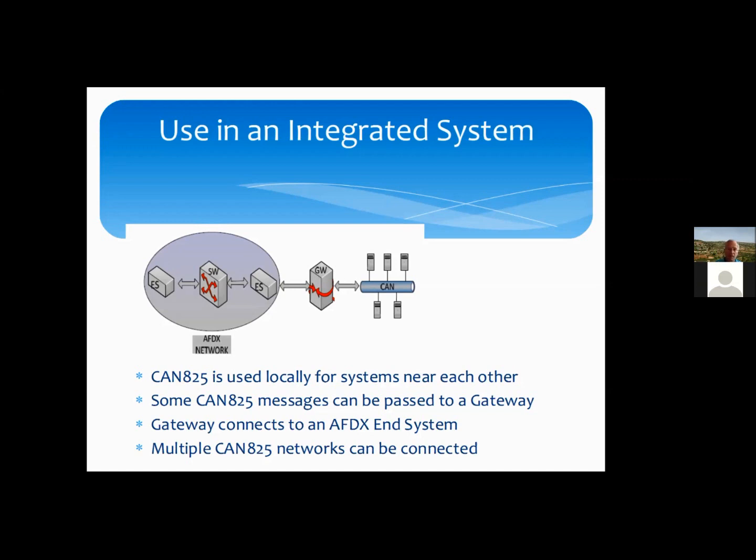the same time. So that way there is a connection, and this connection is brought out in the spec, both in the AFDX spec and in the CAN Bus spec, well, in the ARINC-825 spec. They talk about the use of gateways to share data between the two buses. You can also share data between different CAN buses. So you'll have one CAN bus connected to these 25 sensors and another CAN bus connected to another 25 sensors. And if two of the sensors need to talk to each other, then they can be connected to each other.